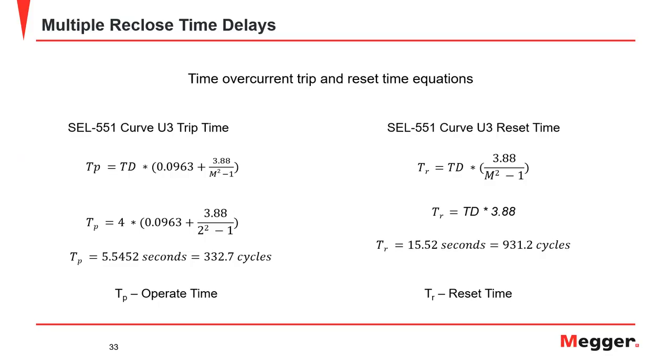What is a fuse dropout? In short, that's when a fuse maybe has been damaged. There's no good reason for it to blow at that particular time, but because of previous accumulated damage, it just fails and opens up. I mean, it's kind of a simple situation.